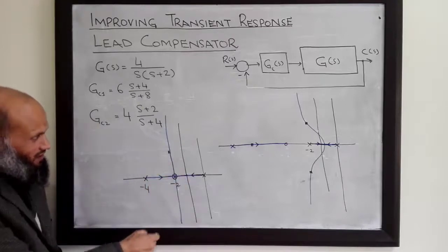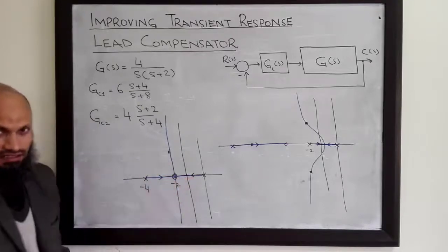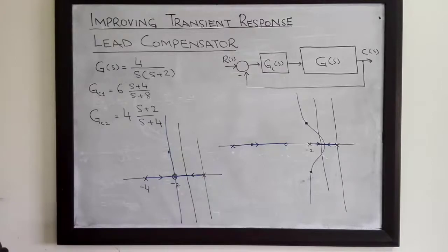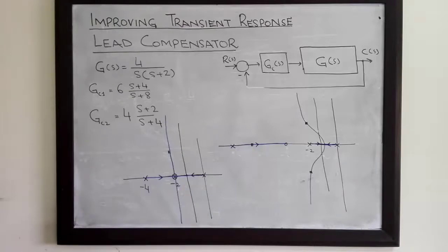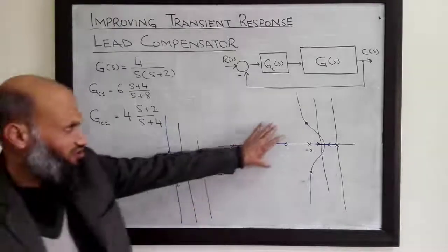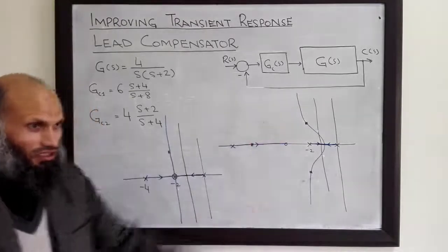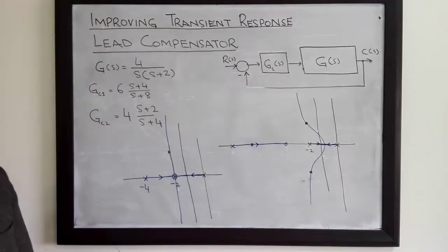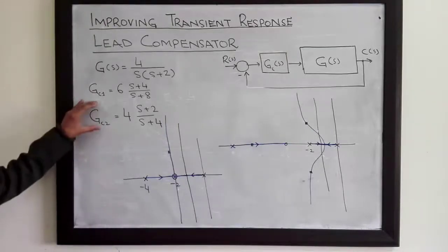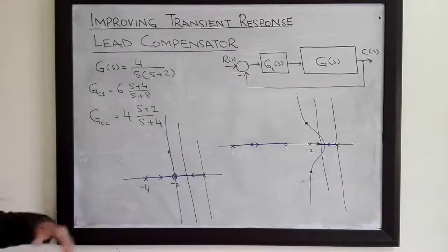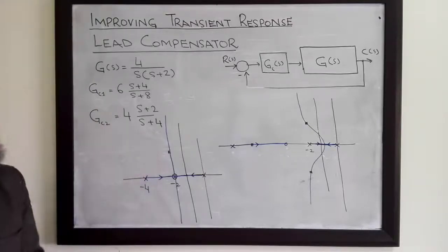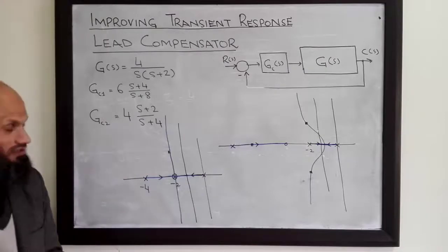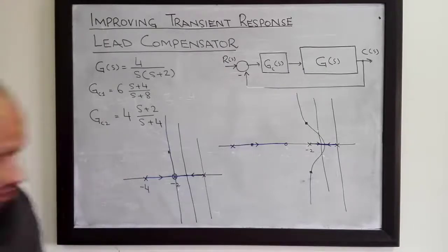However, we can see that the overall system is a second order system. Therefore, the relations for overshoot and settling time will be applicable to a higher degree compared to the other compensator. So as far as transient characteristics are concerned, this compensator is superior. It will give more accurate results. Let's verify these designs with the help of MATLAB and see their performance.